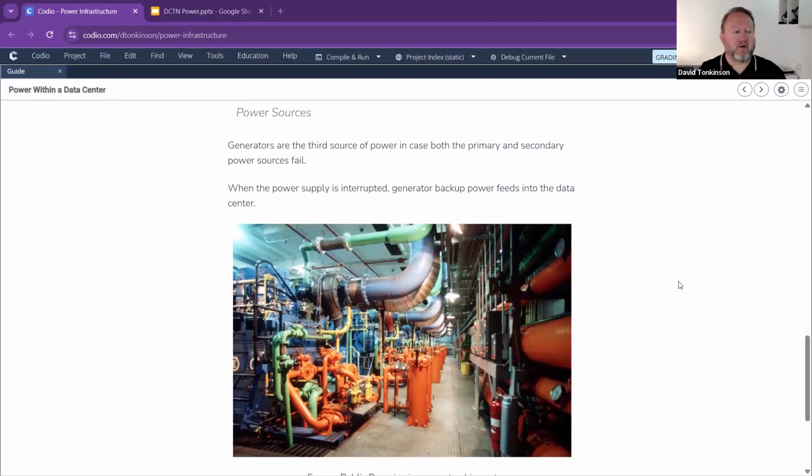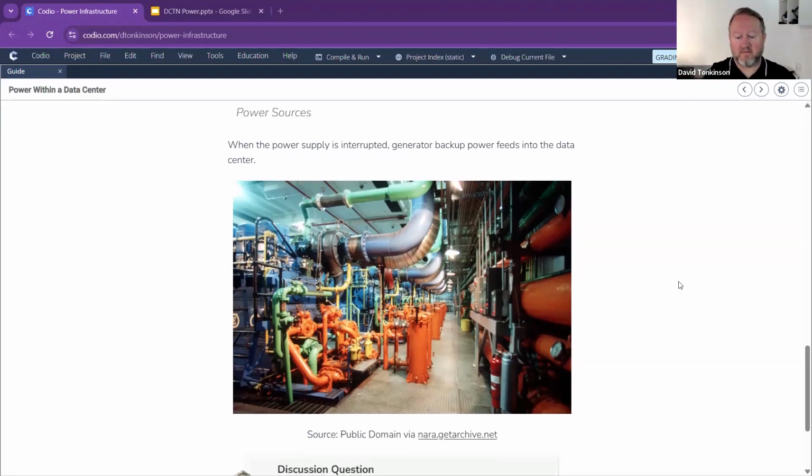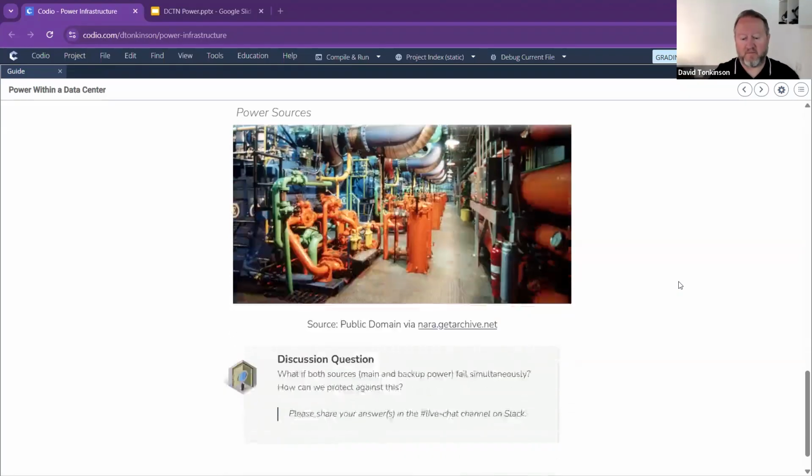And let's just recap that very quickly for everyone. So we have 3 main power sources. Okay, there's the grid, national grid, that provides us the electricity, comes in straight AC. We have batteries as a backup, which essentially is our primary source that it drops over to. Okay, and then there's basically the diesel generators. Now, diesel generators will normally kick in within 5 to 7 seconds of a power outage. At least you hope, anyway.